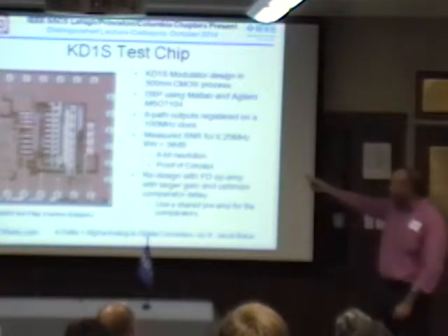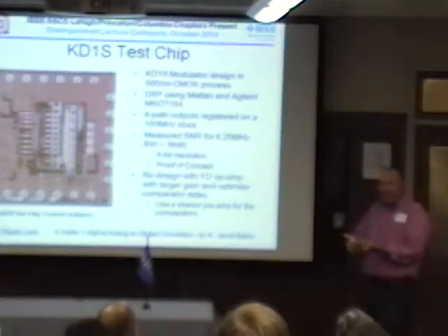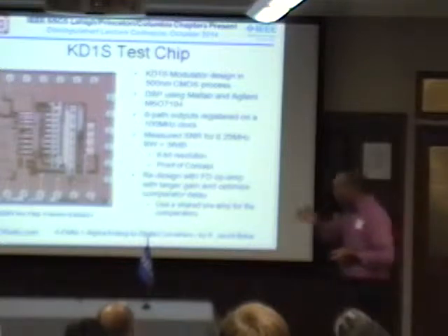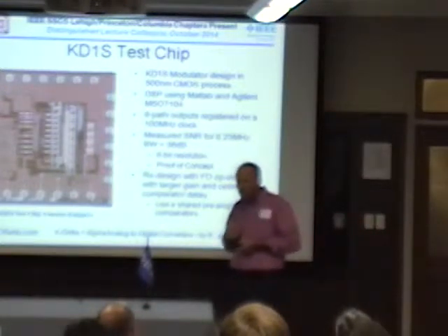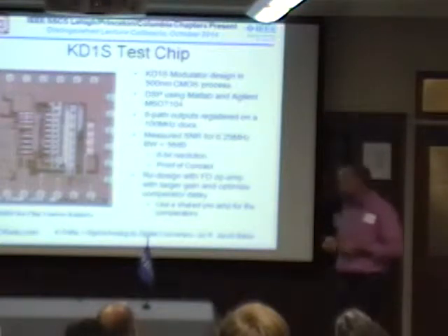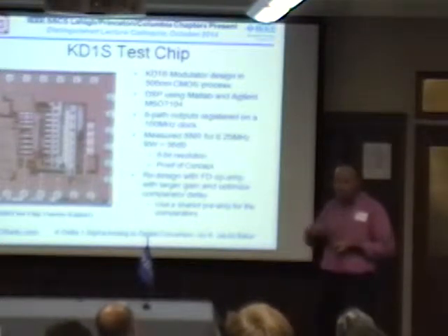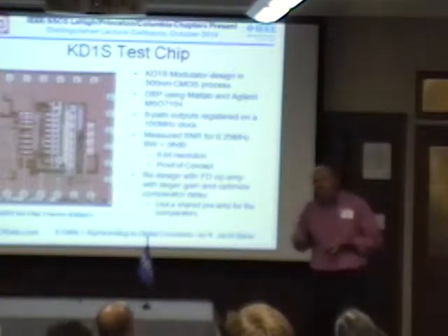So I was thinking, if you're running at 6 bits or something really low, but you're getting like 100 gigahertz, a clock cycle delay of difference between the edges of 10 picoseconds or less, which is very practical nowadays in these smaller technologies, you might be able to use this topology for doing a simple A to D conversion for a SerDes and then adjust the digital signal algorithms to reconstruct the waveform. And I think that's a very practical thing.